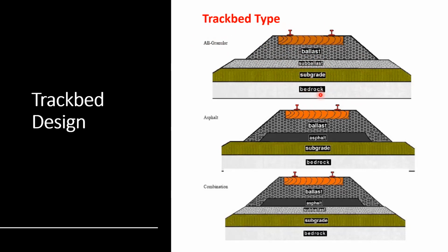Now, bedrock is not a necessity here. Sometimes it's a stiff soil compared to the overlying soil, or sometimes just the natural damping that would happen when the surcharge transfers the load with depth. So don't think of it as bedrock geologically, but more like a refusal surface, or a surface where the effective stress did not increase significantly due to the overlying load from the ballast, sub-ballast.